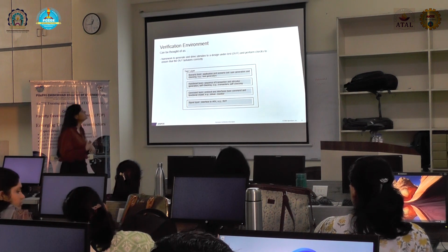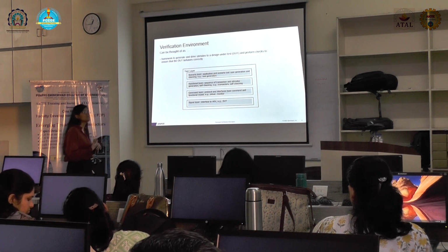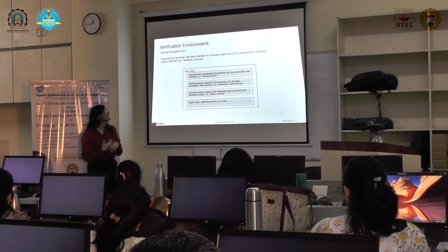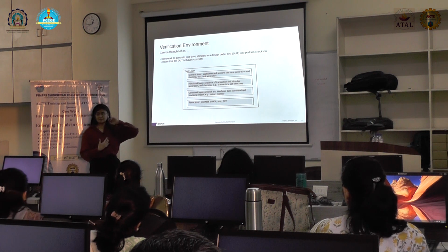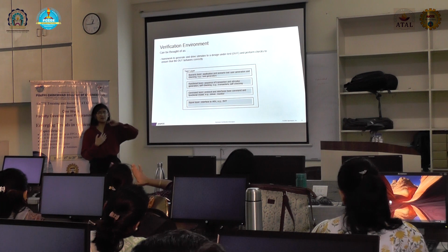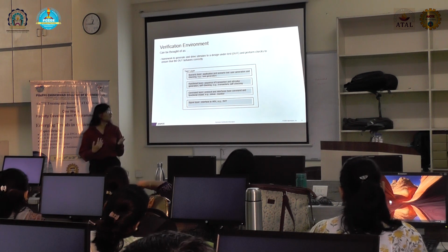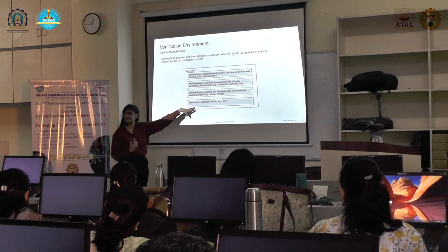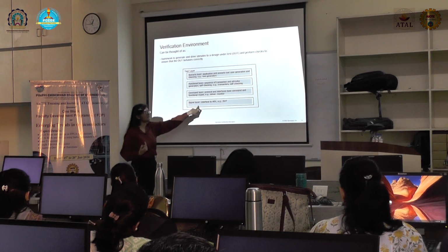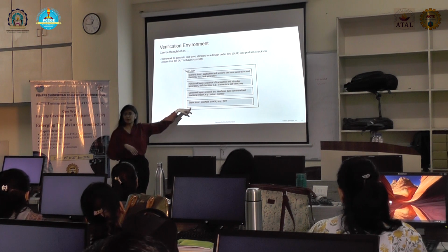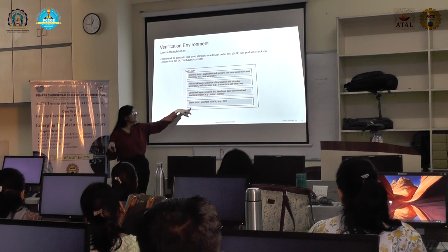Okay, so in SystemVerilog or in UVM, the testbench is divided into sub layers. There is a layered structure that is followed in the testbench for SystemVerilog. It's completely different from Verilog. The base layer, which directly interacts with the DUT, is the signal layer. So we have ports and signals, input signals and output signals, which are directly connected to the DUT.